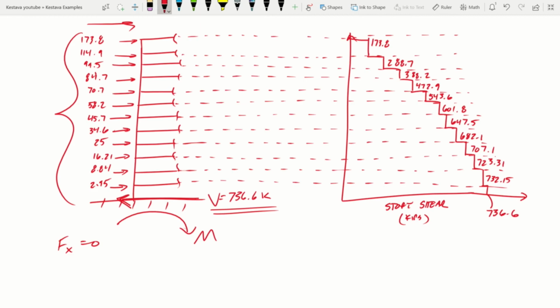So a high rise, you can kind of think about it like a cantilever sticking up out into the sky, and the cantilevered portion is coming from the ground, and then your lateral forces are like your loading being applied to that cantilever. So if you were to turn that whole skyscraper sideways, it would look like a cantilevered beam coming out of a wall. So you can kind of think about it like that.